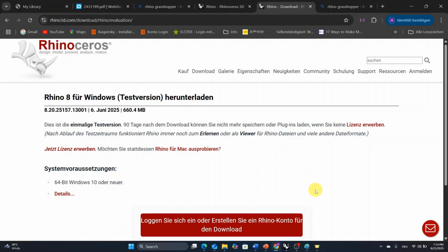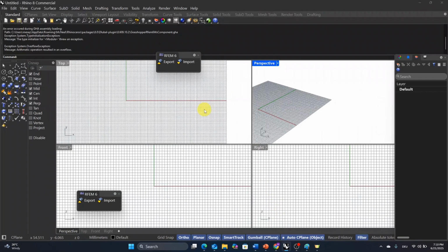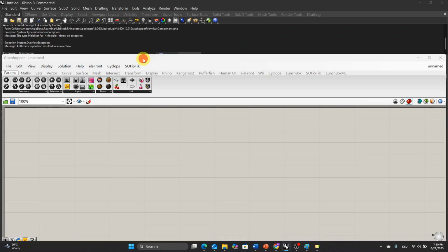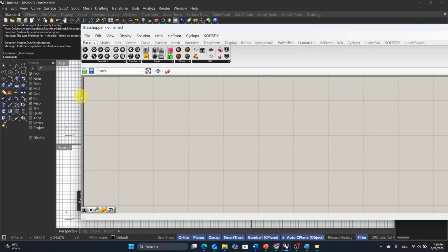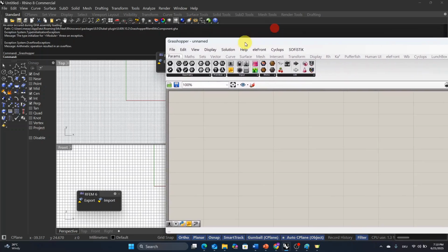I have already installed Rhino 8. As you see, Rhino 8 is similar to AutoCAD and other drafting softwares. What I wanted to show you is the Grasshopper visual programming tool that will help us to create geometries programmatically. You will find Grasshopper at the Standard toolbar. Its symbol is a green ball. Click it to open Grasshopper. As you see, a new window or canvas appears.